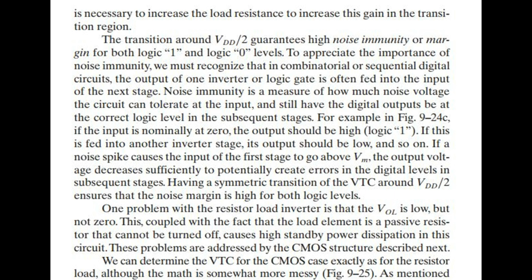To appreciate the importance of noise immunity, we must recognize that in combinatorial or sequential digital circuits, the output of one inverter or logic gate is often fed into the input of the next stage. Noise immunity is a measure of how much noise voltage the circuit can tolerate at the input, and still have the digital outputs be at the correct logic level in the subsequent stages.